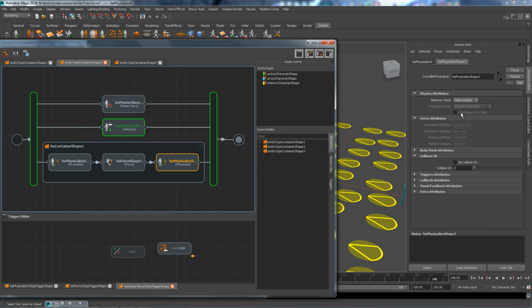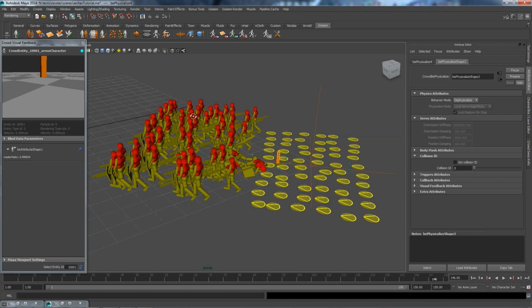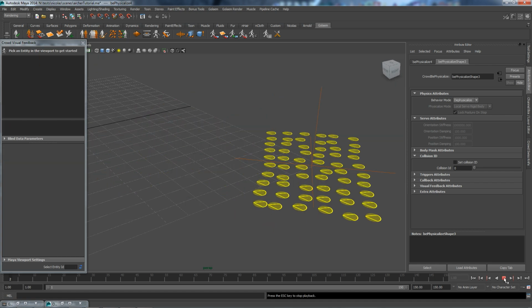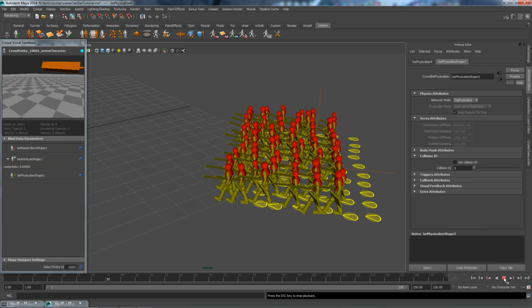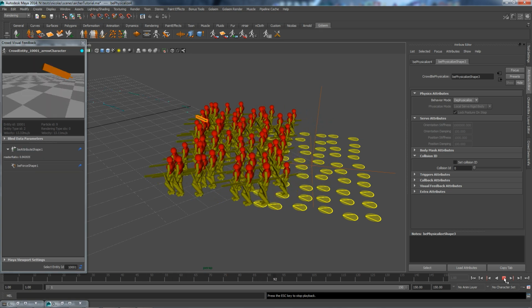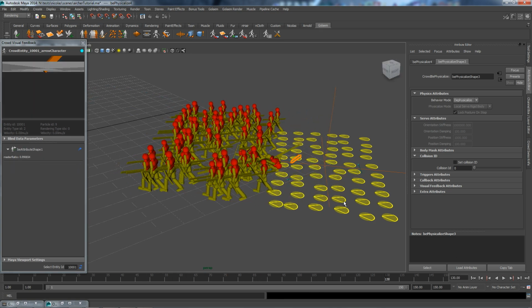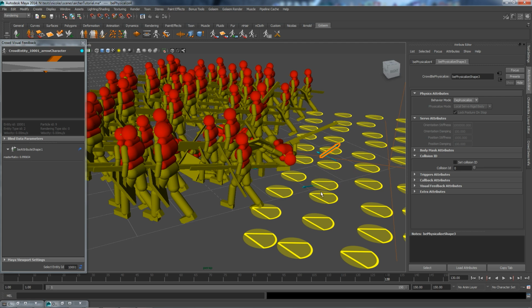You may have noticed that there is an option which is lock posture and stop, which, as the name tells, as soon as that behavior stops, it just freezes into the current posture. It's actually grayed out. It's just a bug in the interface, so I'm just going to fake it here. I'm going to physicalize local servo or whatever, which allows me to check that box, and I can go back to dephysicalize. And now I have set my arrows to lock postures on the final frame, and when they hit the ground, it just freezes into the current posture.